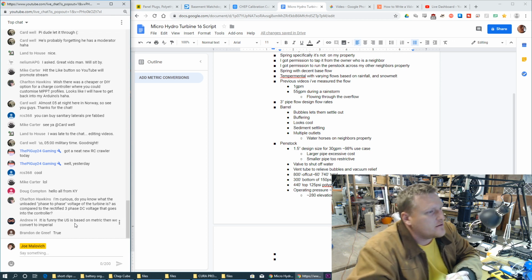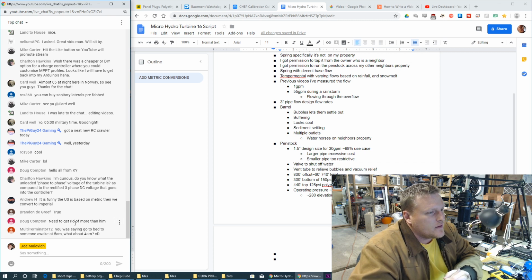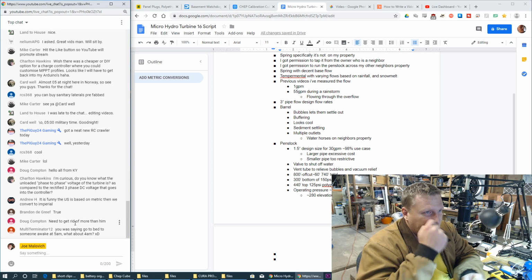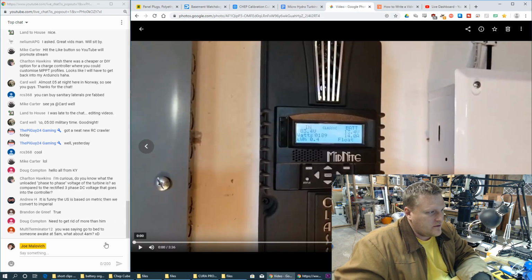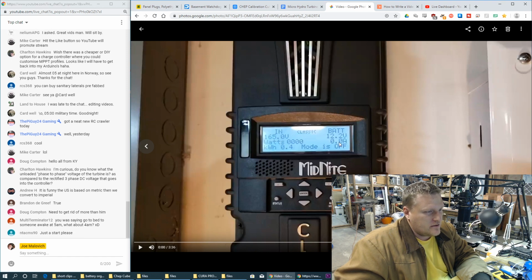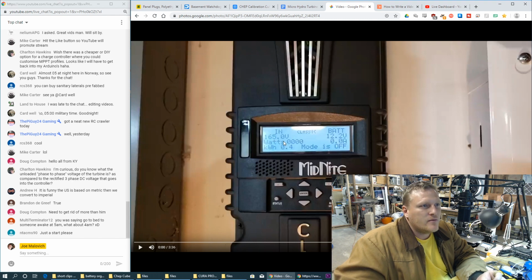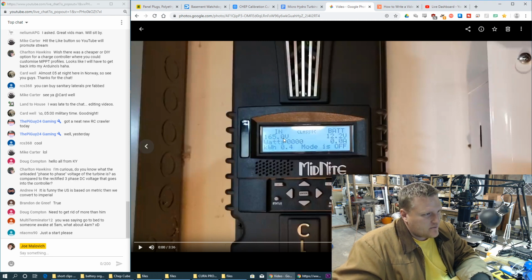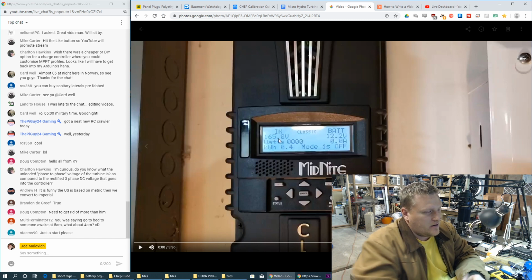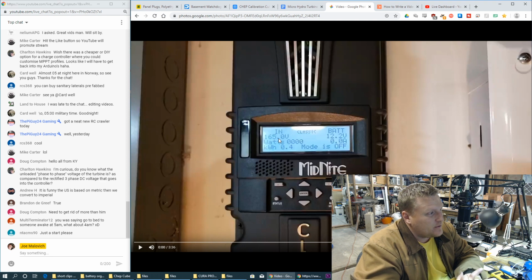It looks like my chip cube is getting close to being done. So my open circuit voltage, if we go all the way to the beginning, we see an open circuit voltage. Notice there's no amps coming off of this, no watts. This is 165 volts, and that's with 2 jets. With 1 jet, it's approximately 156 volts. So we get a little bit of extra voltage, overcoming friction and just powering the fan, if we add in 2 jets. And this is rectified DC, so the AC would be around 110 volts, I'm guessing. So I could potentially run some AC equipment directly off of 2 of the phases.